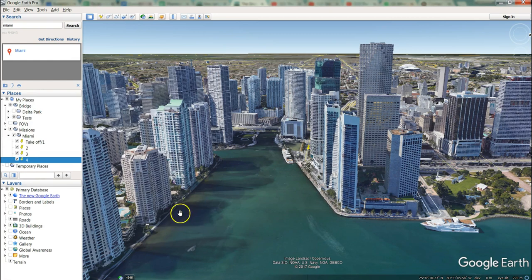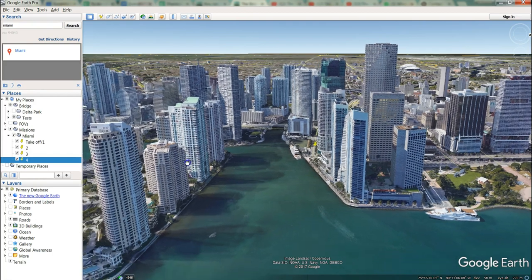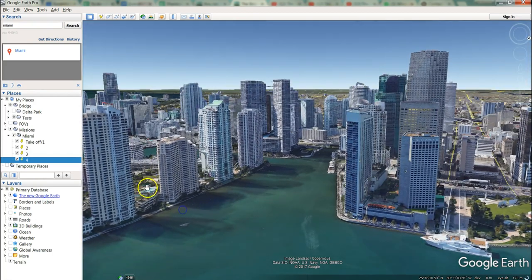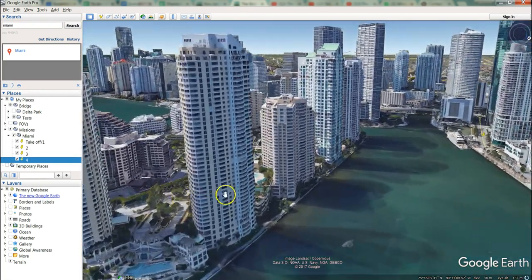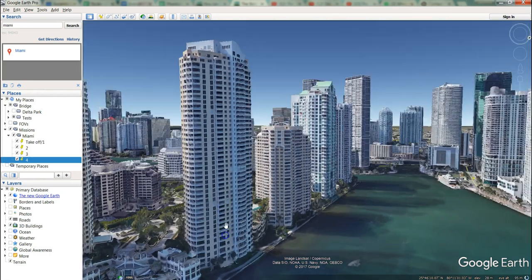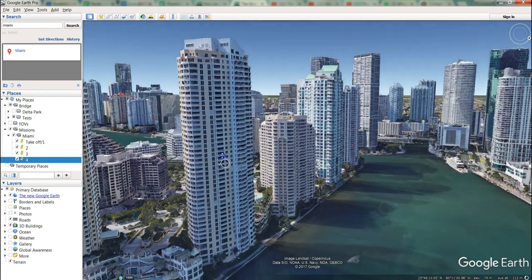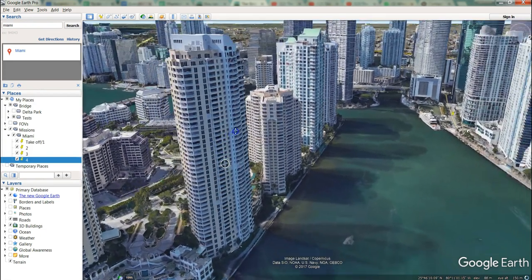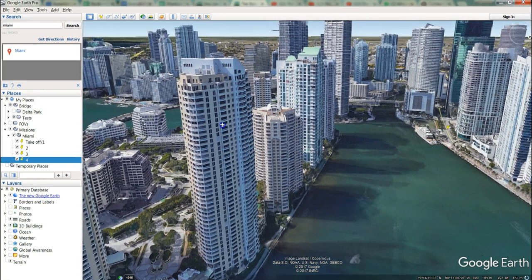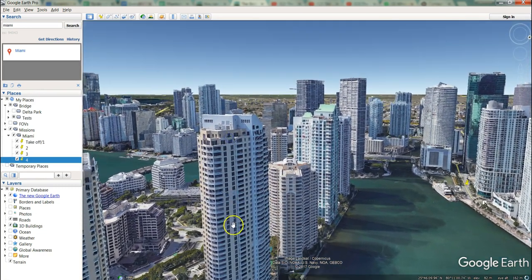Now, a useful way to change altitude, let's just say, for example, we were going to do something really simple, like we wanted to go in front of this building here and do a simple rise shot. We would drop a waypoint. I would then hold the shift key, and push my mouse upwards to climb in altitude, and then I would hold the control key and look up. And that way you can go up or down in altitude. But you'll figure all of this out when you play around with the various Google Earth navigation features.